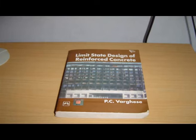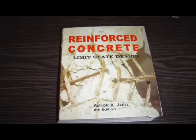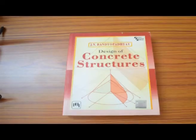Now the other load is the one that will come in a particular case. Sitting here you have frames, tables, and many other things. What is the weight of that part? We call it super-imposed load or live load. This information is in IS code. Then we have earthquake loads and wind loads. Dead load and live load act vertically. Wind load, say cyclone, and other things act on the side. Earthquake load also acts in the lateral direction.